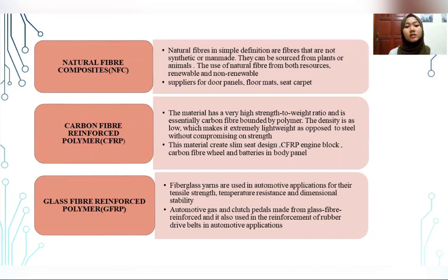For glass fiber reinforced polymer, fiberglass yarns are used in automotive application for their density, temperature resistance, and dimensional stability. Automotive gas and clutch pedals are made from glass fiber, and it's also used in the reinforcement of rubber drive belts in automotive application.